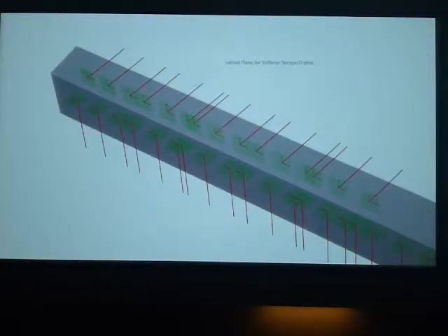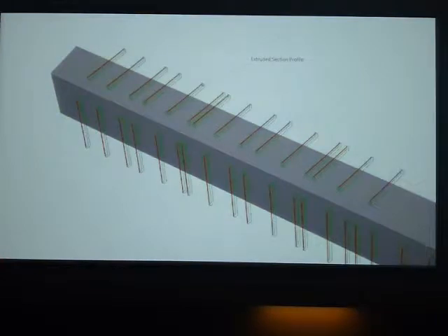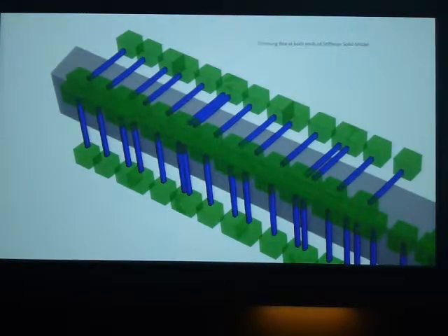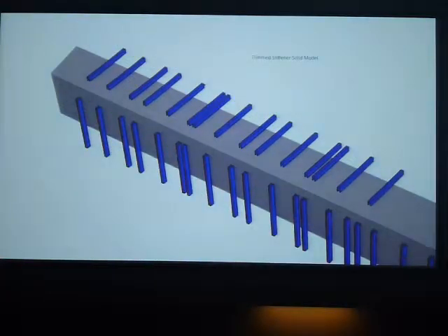So there's a plane that's also defined and saved as an attribute on this wire. And then the section profiles are lying on this plane. And then these section profiles are extruded along these wires. Then we bring in all these trimming planes that we saved as attributes and we create trimming boxes on them. And these trimming boxes for all stiffeners are now again stored in wireframes as attributes.